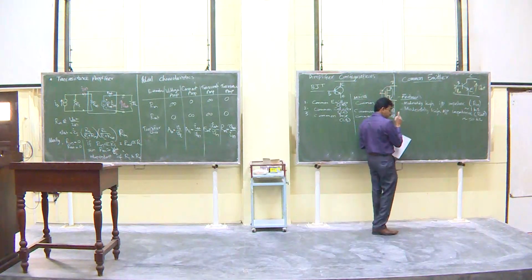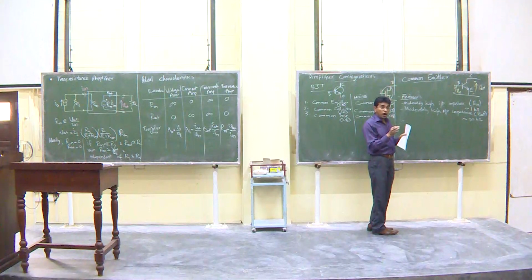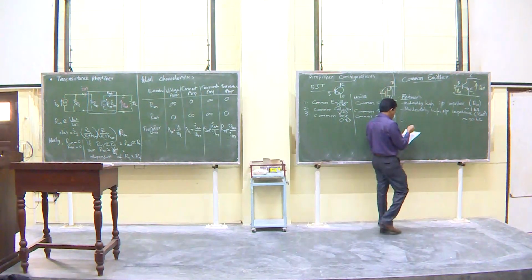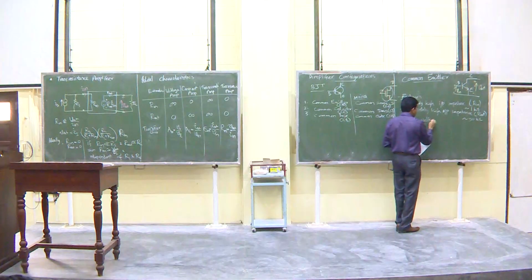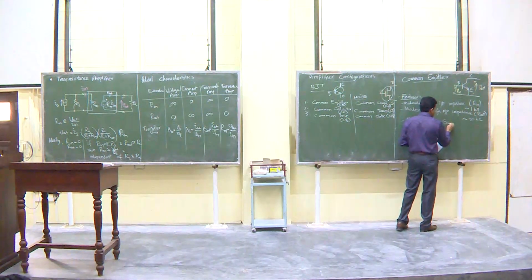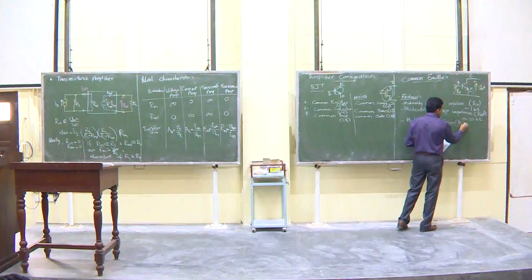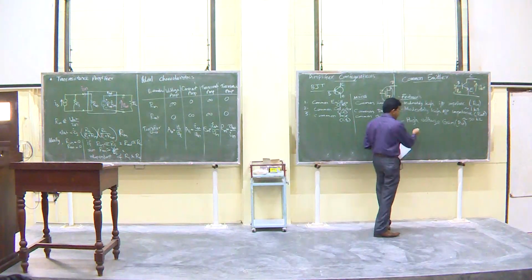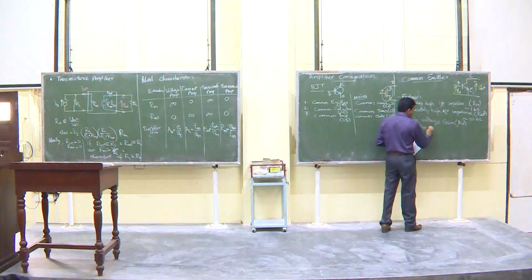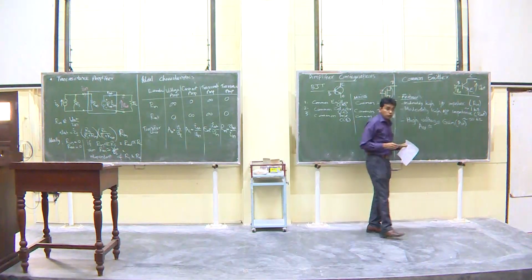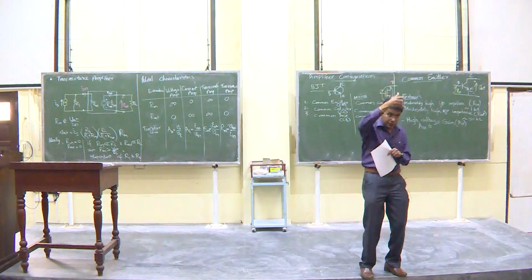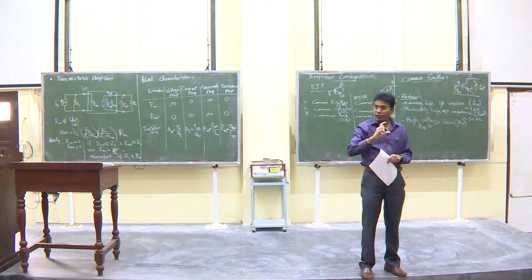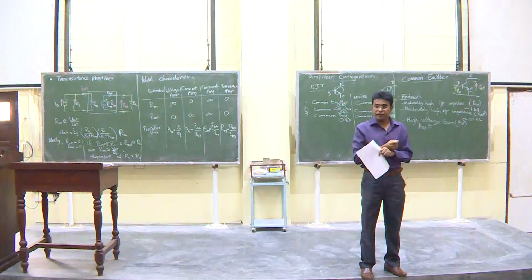But the specific feature about this is very high voltage gain, AV. Now, as I mentioned earlier also, AV is roughly equal to whatever is the resistance in the collector branch divided by whatever the resistance in the emitter branch, including the emitter spread resistance.